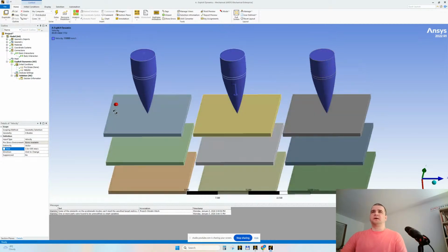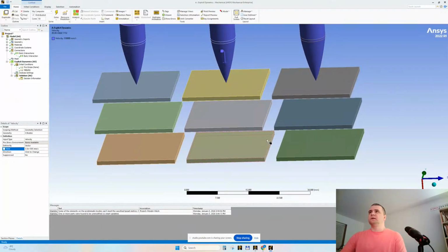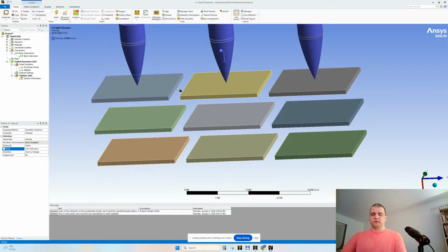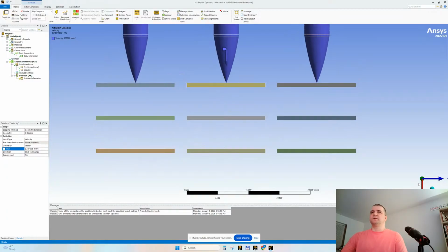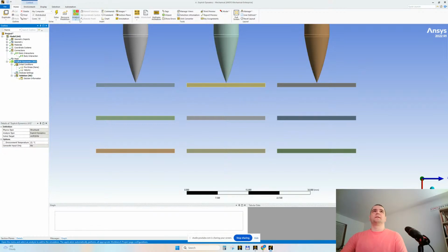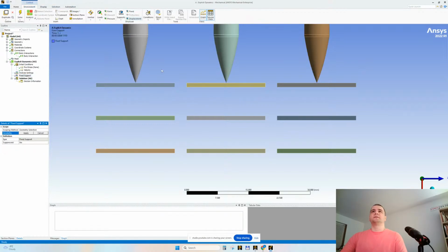Because the plates are kind of drifting into cosmos, let's fix their peripheral faces. Control F to select only faces. If we click any arrow, we can reposition, redirect, let's say, the views. And yes, let's go here for fixed. And we will be selecting, because we don't have proper selections.